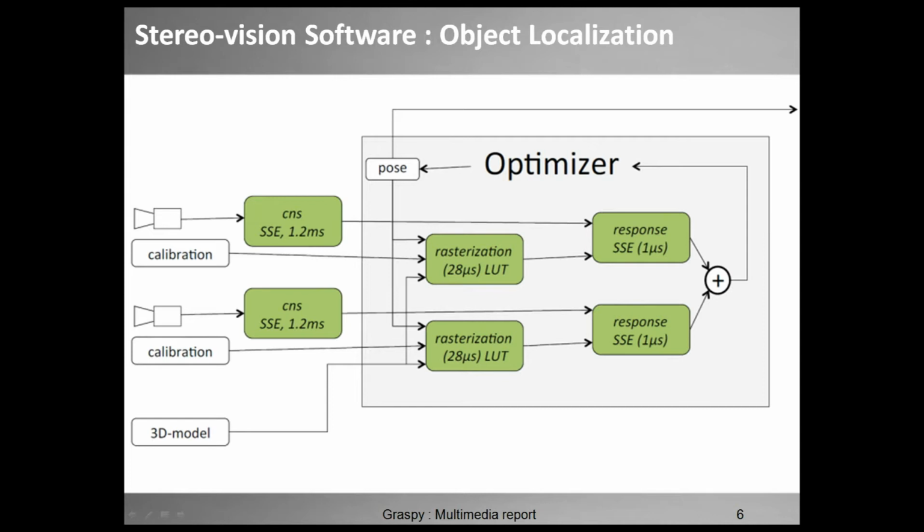The software globally searches through the image with a coarse raster of poses spread over several frames. Once a reasonable response is found, it is locally refined by changing the pose towards growing responses. After that, the cup is tracked by applying this refinement procedure every frame. The system runs at the full frame rate of 30 Hz.